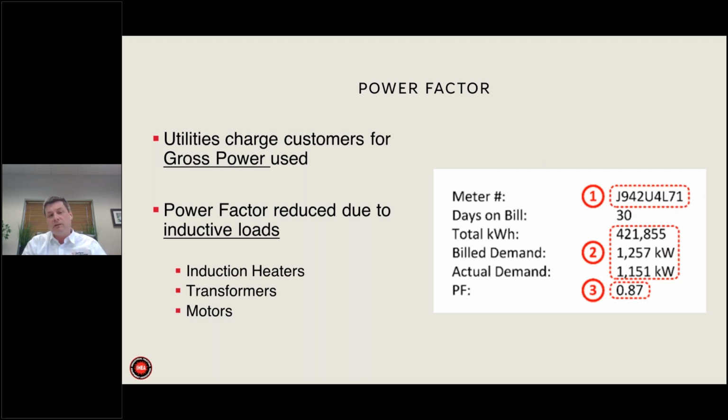The other thing you have to take a look at is what the efficiency of your transformers is. And then also, do you have any very large motors? Especially when you have a high pressure gas quench, those motors can get up to 1,000 horsepower. That's a pretty big motor, and if you're not careful, it can reduce the power factor of your facility.